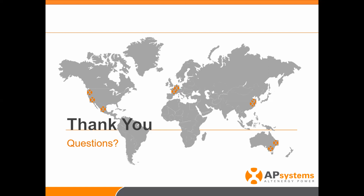And the reason we did that, just so it's super clear, is NEC requires arc fault breakers. In the 2014 code, they required arc fault breakers in all bedrooms. And where do people put their offices? They put it in a bedroom that is now protected by an arc fault breaker. So there's two problems with that. Number one is trying to pass a PLC signal through an arc fault breaker is impossible. And in attempting to even do it, you get false trips on those arc fault breakers. And I'm sure many of you on the call have experienced this type of issue.